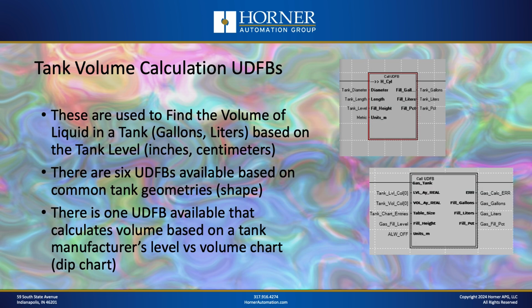Okay, next we have tank volume UDFB. So these are user-defined function blocks that were customer requested that allow you to calculate volume based on the level of a tank with either a known geometric shape or where the manufacturer has provided a data table of level versus volume for that particular tank. So we've got those two different categories that we can handle.